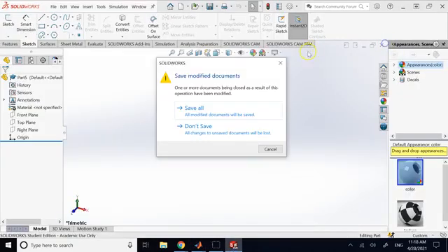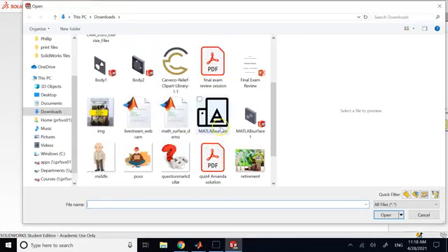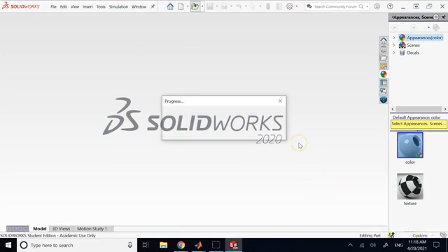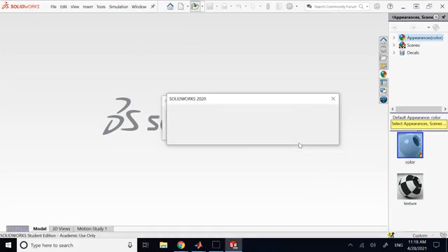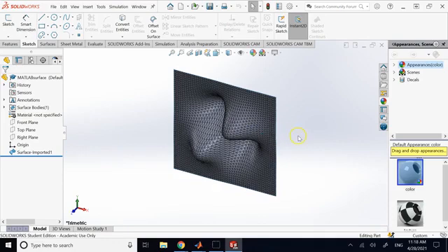And guess what? Now I can go into my SolidWorks or CATIA, and I can open this mesh file, because that's what the CAD software understands. Now, SolidWorks is not the best for importing STL files, but if the STL file is not huge, typically less than 40,000-50,000 points on the surface, it can import it. If the number of points is relatively high, it imports it as a surface, not as a solid model. And this is a surface, actually, and that's what we wanted.